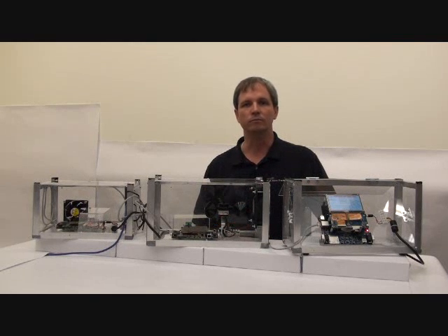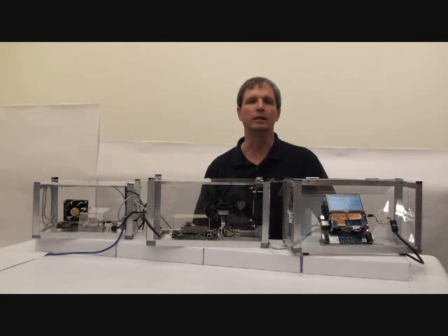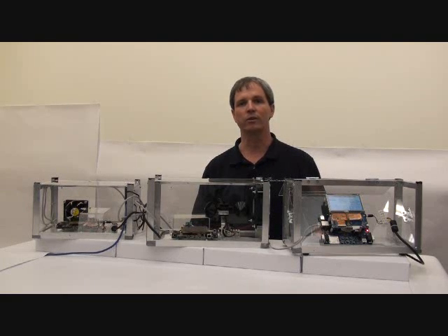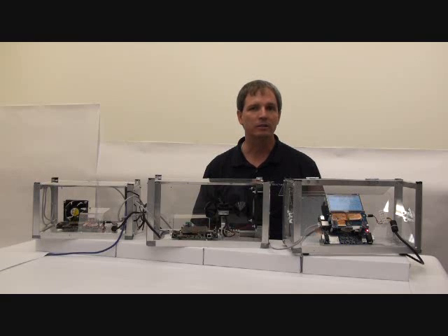Writing straight C code, you've got to write everything yourself. Don't have any OS services available to you. When I looked at the .NET Micro Framework, I saw a lot of these pieces just built in. That made it really exciting. I had GUI components that I could just call into. Writing drivers for things like the serial bus or I2C or even the GPIO usually takes just a couple lines of code. There are also things like threads, XML parsing, network support, TCP/IP stacks. All of this stuff is just built right in.